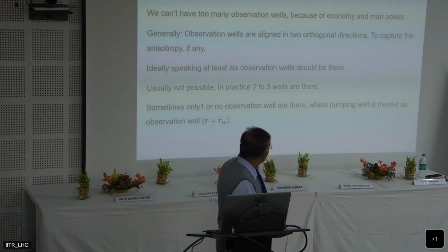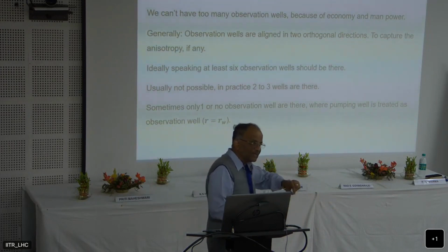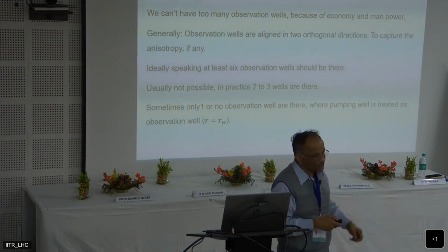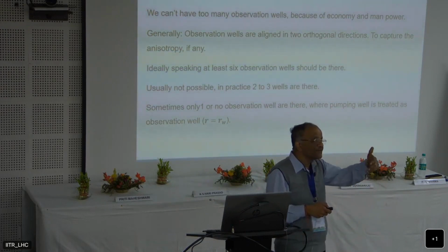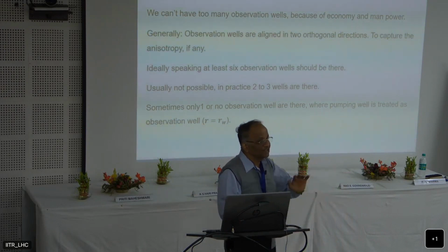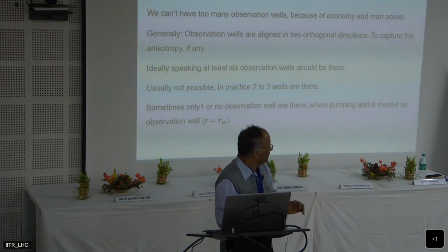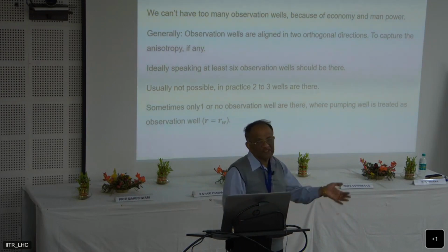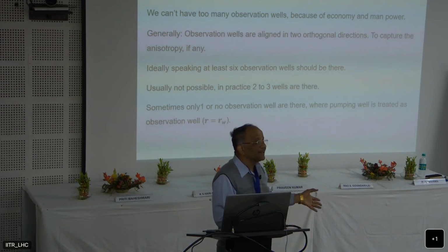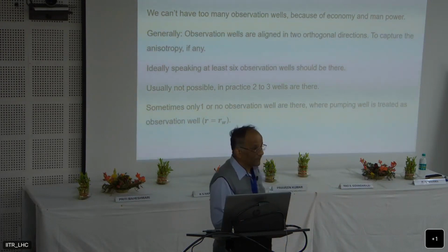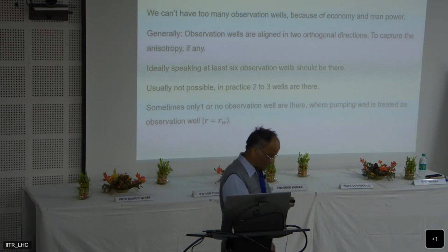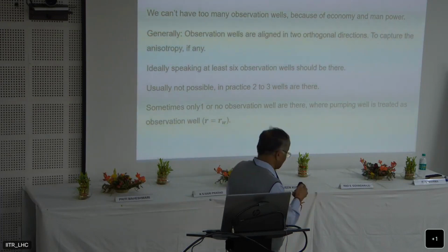So you can also do a pumping test with only the pumping well itself. That means you try to find the drawdowns within the pumping well. And from that you can also get the recovery data. That means once I stop pumping, the water will rise. That data is called the recovery, and that data can also be used for finding out the aquifer parameters.